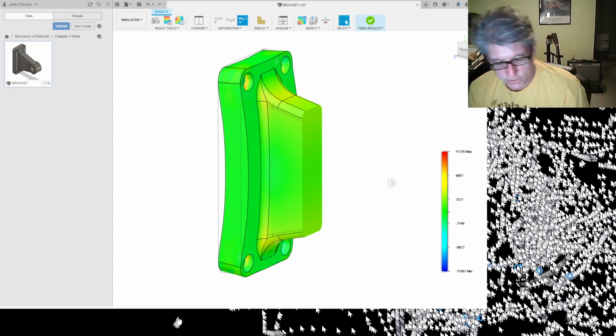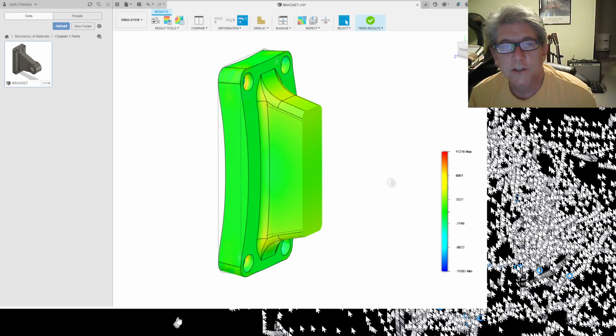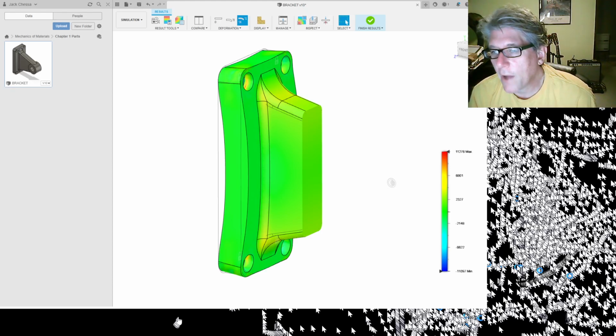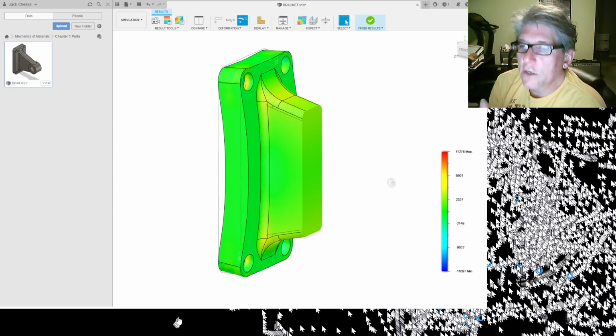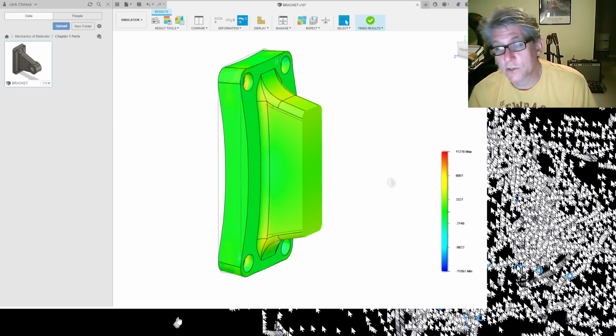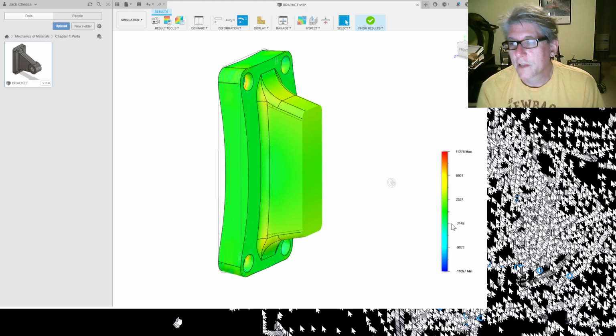And then I just do the screen capture, like on Windows, it's the Windows Shift S, and just grab it. But when you do, make sure that you get the legend. Without this legend, right, it's meaningless because you need to know what the stresses are. First of all, you need to know what you're plotting. Sometimes students just plot the colors, and you don't know whether it's strain, displacement. Forget about what the values are. Okay, so it's really a meaningless exercise. So that's one thing you want to be careful of.